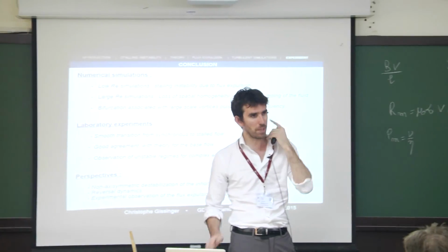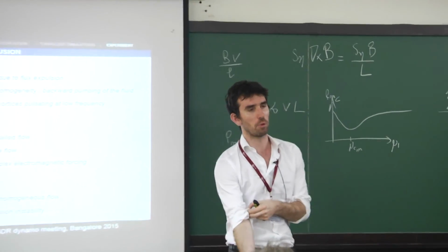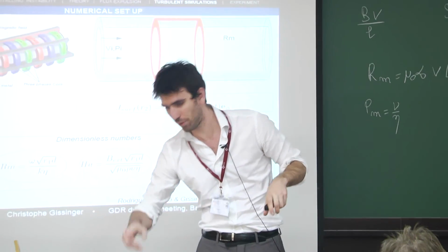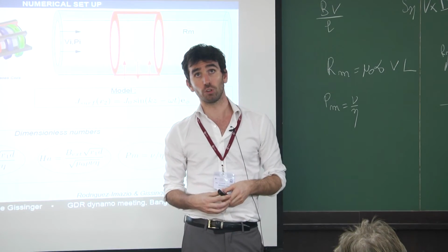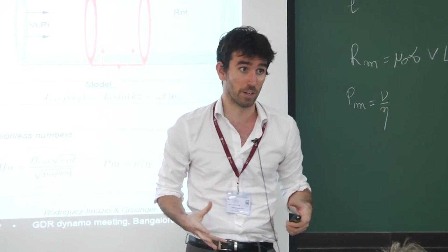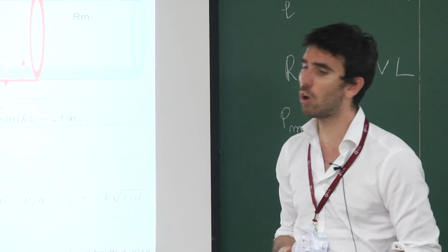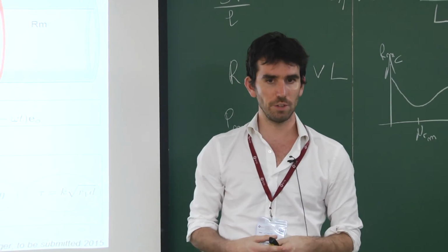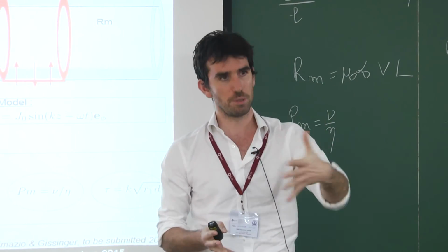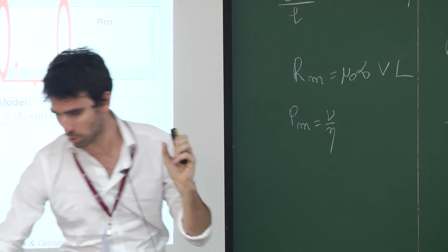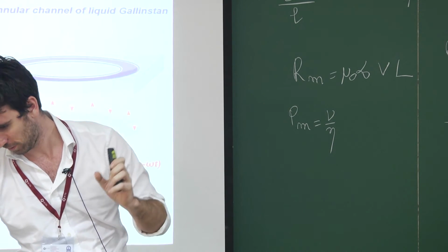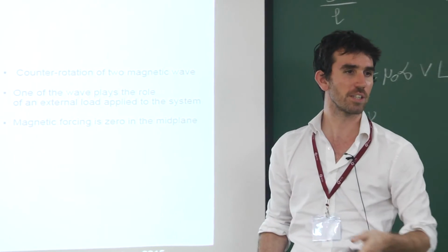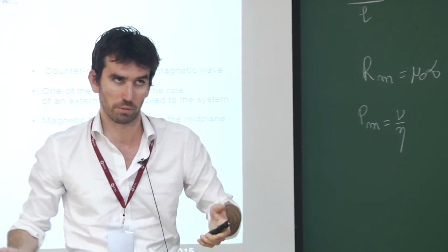So, the biggest experimental pump which has been built, which is based on this configuration here, the Rm is of order of hundreds, it's very big stuff. The smaller ones, which are used for secondary cooling systems, are around 20. And around 20, they already see this weird low frequency pulsation in the flow. Now, in the small scale experiment, I don't want to tell you the Rm, but of course it's very small, of order 1.